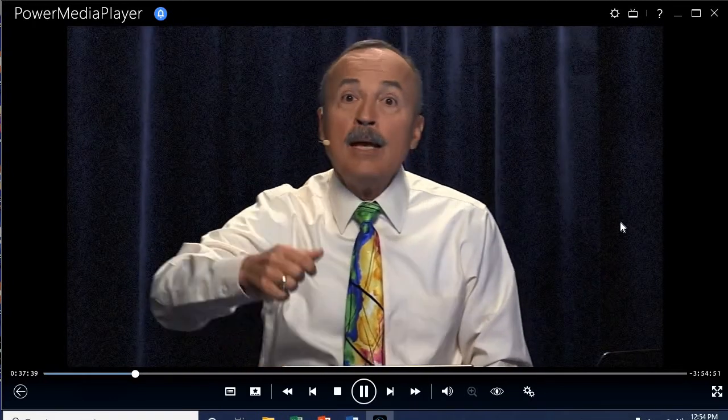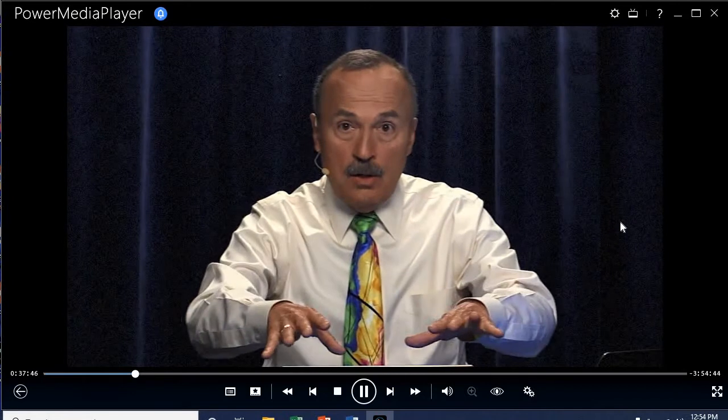The wire we're going to run to that is called a grounding electrode conductor. So now we have an electrode because we're going to connect to the earth. That's the best we can do. We're going to run a wire to it, a grounding electrode conductor, and then we're going to connect that wire to something that needed to be grounded.